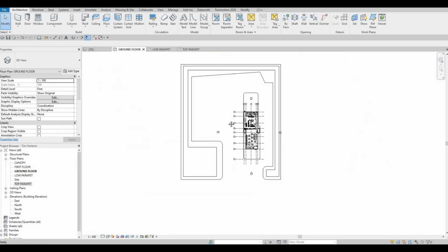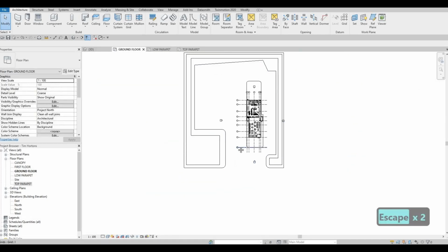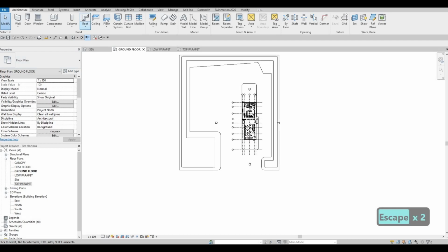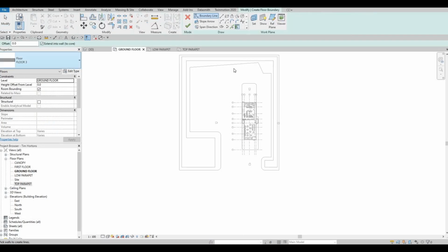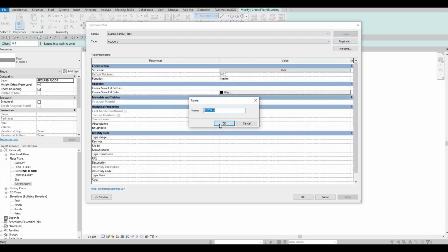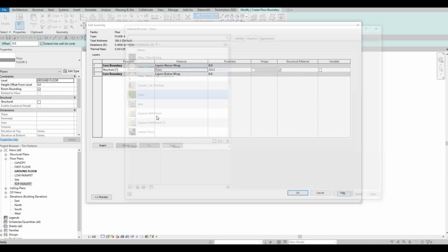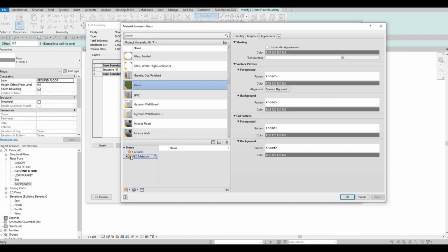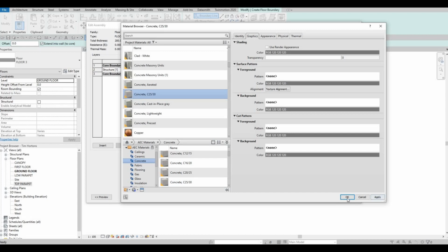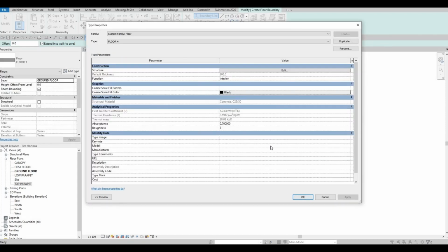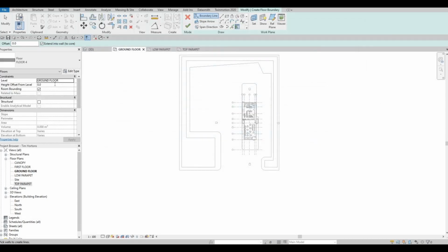And then go back here, we need to add the ground itself. So another floor, edit, duplicate, this will be floor number 4, edit, we're going to add another concrete floor, but we want to make it a different one because we're going to set a different material on there. This will be -200 from the floor.